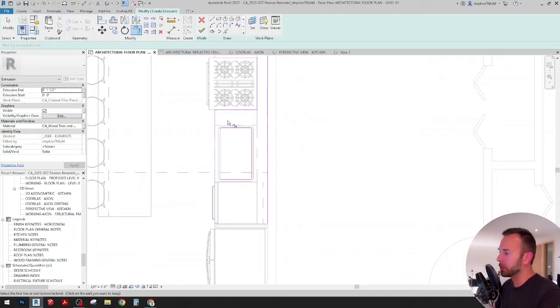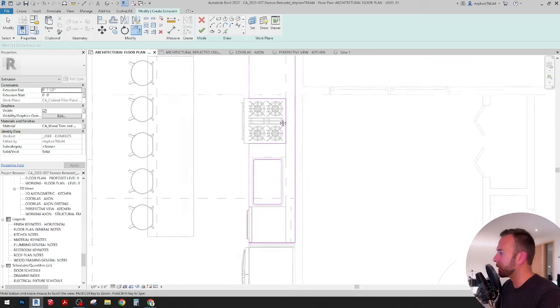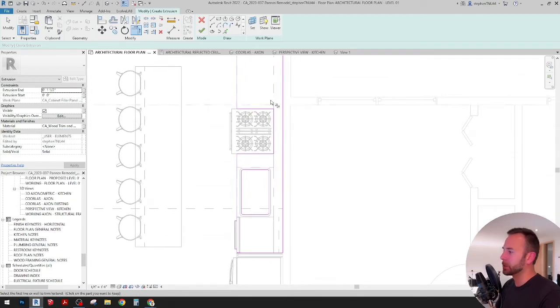Casework or cabinetry is actually typically at 2 foot 10 inches. So the countertop depth is actually always a 1/4 of an inch shy of where people think it is, but that's to allow for shimming of the different cabinets and things like that that eventually typically get it up to about 3 feet. So I like to just keep it at that flush number there.